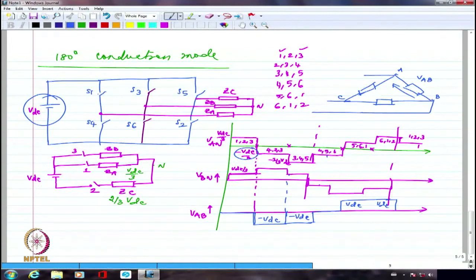That is one problem. The second problem is, all the waveforms that we have got are far from being sinusoidal. They are not sinusoidal. And if I have to adjust a motor drive to a particular frequency, and then I want it to run very exactly at that particular speed without any torque pulsations and so on and so forth, I definitely need to make sure that the voltages are somewhat close to sinusoid. I may not be able to get exact sinusoid, but I may be able to get close to a sinusoid by eliminating at least some harmonics.